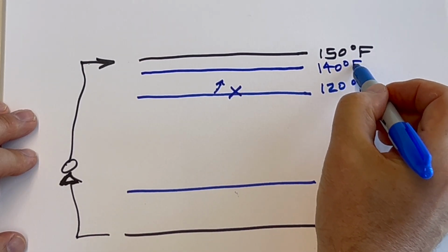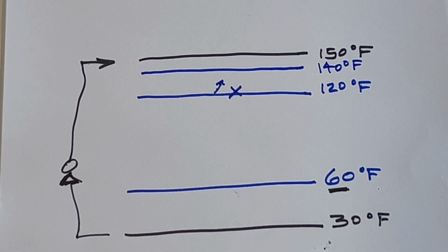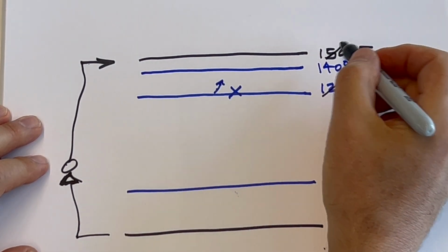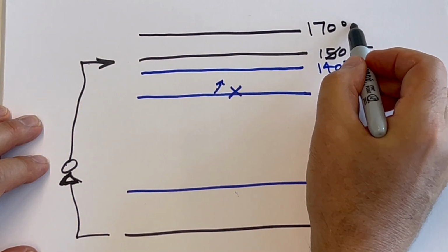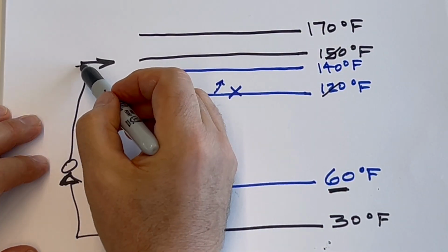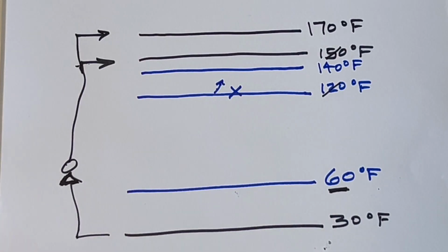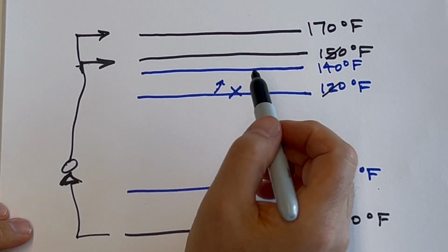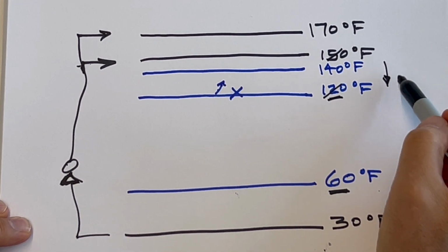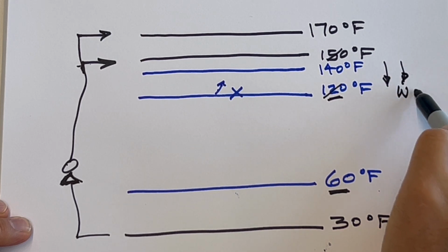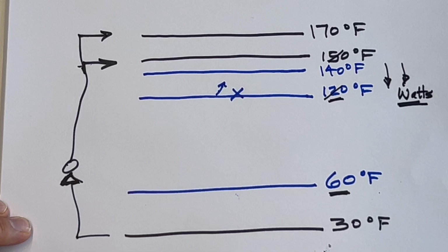If we operate at 140 degree hot water temperature, we use our rule of thumb, and the refrigerant temperature is way up at 170, and the compressor is working even harder. So, very important set point on a domestic hot water heater that's being used with a heat pump. The lower the set point, the lower the power, and the higher the efficiency of the heat pump.